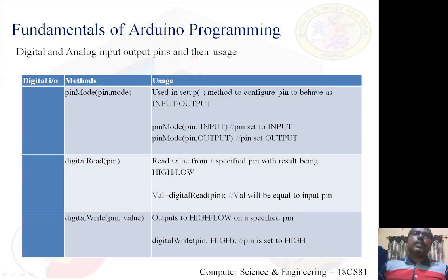So there are some methods, we will have a look. Pin mode. The pinMode method is to configure some pin as input or output. The pin to be configured as input or output should be the first parameter, and mode here is a constant, either INPUT or OUTPUT.